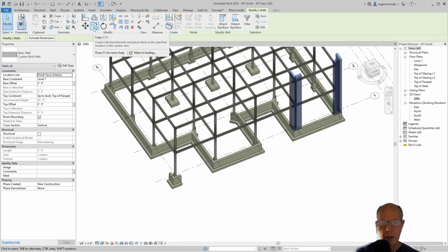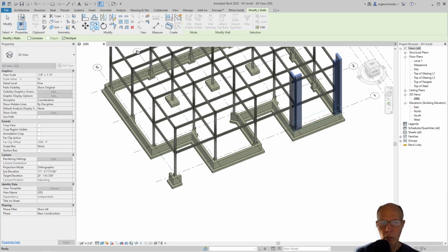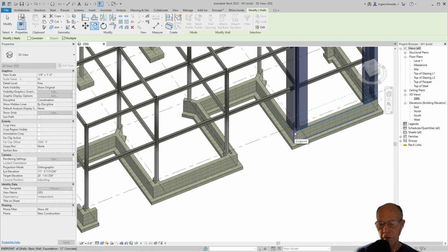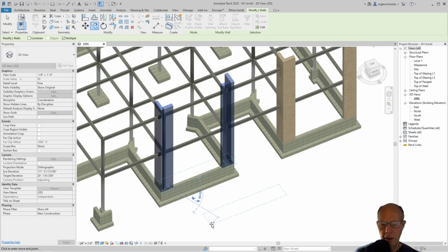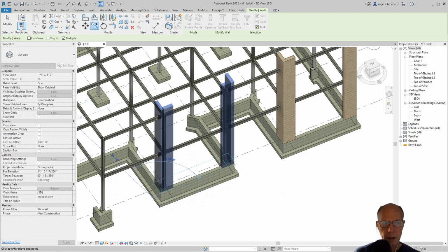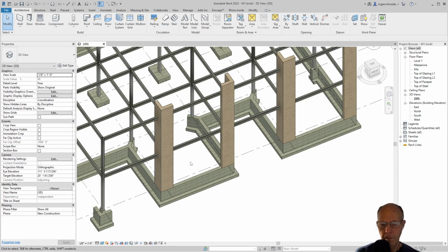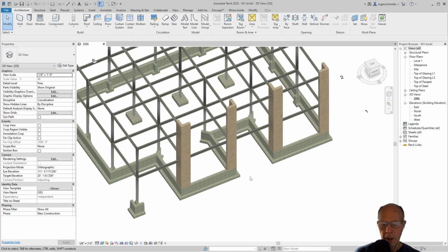And now I can use the copy and move tool. And I can come in here and touch this front very edge corner. I'll get an endpoint indication and the wall's highlighted. I can click that and drag this over to here, exactly the same place, and click off, and now I have a duplicate set of walls created. Now, if that doesn't work for you very easily or it's troublesome, you can just redraw these walls. Remember that they have to be 4 feet.